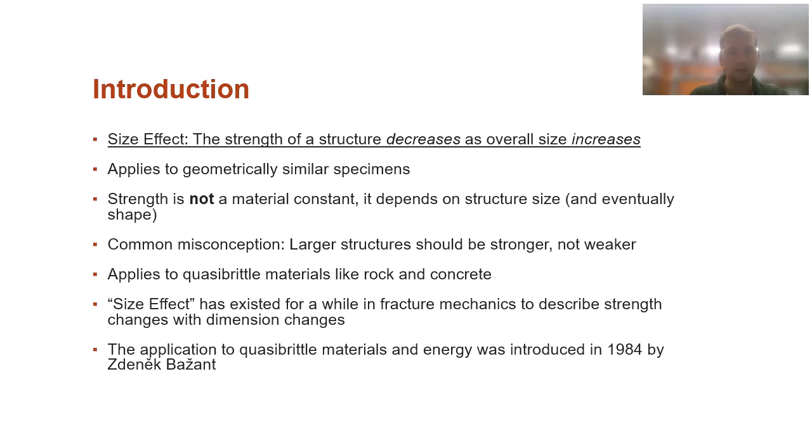But essentially, concrete and rock is our main focus point for this whole study today. This is a common misconception to me, because strength should be a material constant in my head. And similarly, you would think that strength would be either constant across sizes, or it might even get stronger as a structure would increase in size. It's actually the contrary. Bazant's size effect study found that large structures actually are weaker as the size increases.